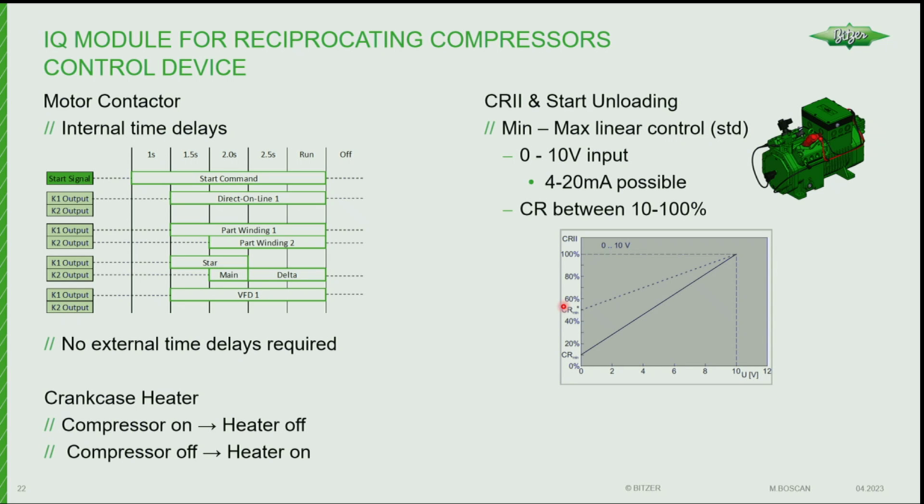If you run at 0, the lower limit of 10%, again, it will never turn off, but what it will do, depending on the refrigerant, after between a minute and 2 minutes, is de-energize one coil and load up the compressor to get some mass flow back over the motor to cool it down. But after 30 seconds, it goes back down to 0 mass flow.